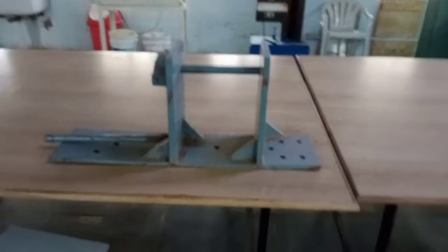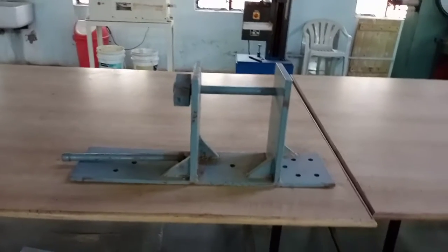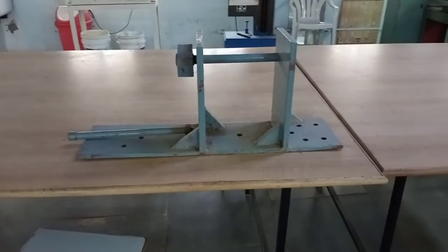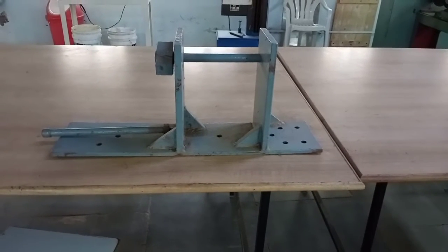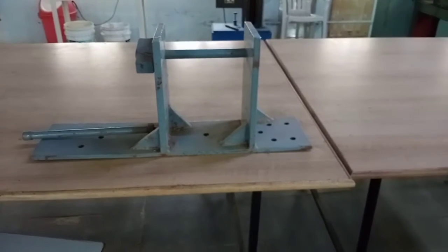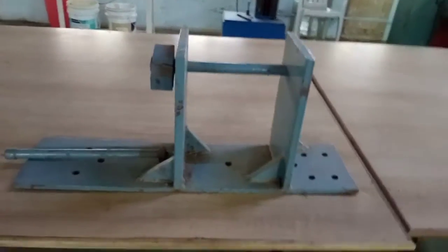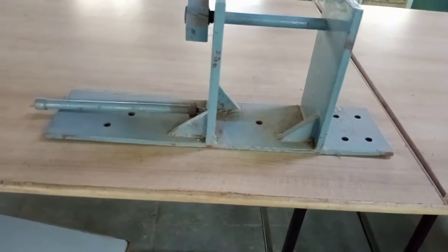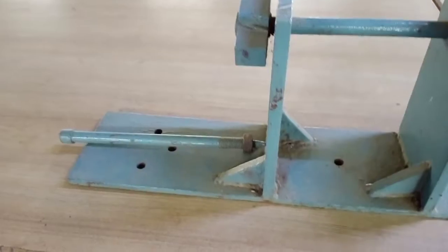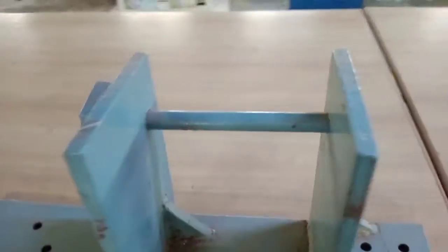Horizontally we have a steel frame, a steel plate fixed. We are taking a 10 to 15 mm thickness sheet, depending upon the random value of load. You just see that. And we have two vertical rods welded to the bottom sheet. For support, we are providing brackets here, one more bracket on the other side, and here also one more bracket, to have support, otherwise it may fail during its operation.